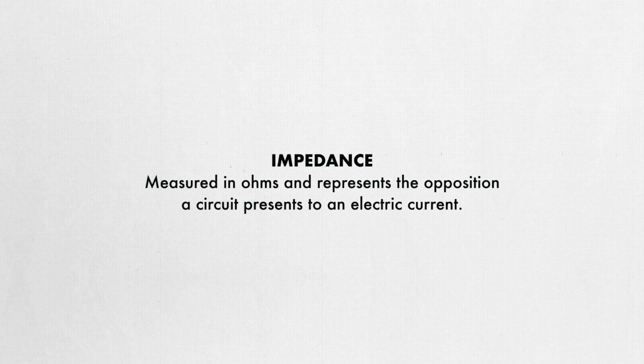There are two basic factors to keep in mind when choosing an amp that is compatible with your speakers: impedance and power. And as you'll see, these two factors are very closely interrelated. Impedance is measured in ohms and refers to the opposition a circuit presents to electric current. The first step in choosing an amplifier is to determine the nominal impedance of your speaker or speakers.